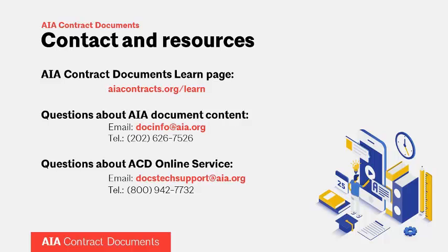Does design assist or delegated design obligate the owner for general contractor selection for construction services? If I'm understanding the question correctly, if you're doing design assist services, does that mean the owner then has to hire that company to do the actual construction? Not necessarily. Usually that's the way it works. Usually if you've got a sub-trade who's doing design assist services, they're doing it because they have particular knowledge about their system, and they're giving the design team input early on about that system. Usually they're going to be hired, and the expectation is that those subs or that construction manager is going to be used on the project. But that's not necessarily how it has to work.